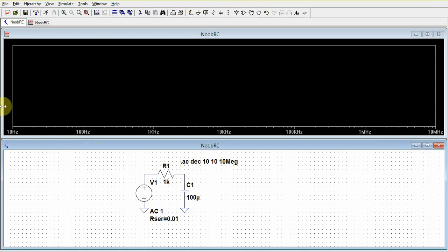And you can see this builds up our plot, but it is empty because we haven't chosen which signal we want to plot. We'll do that very simply by clicking this, and this is a voltage probe. When you do this, you can see in the bottom left corner, click to plot V(N002). So this would be node 002 of the circuit. You can also do that here.